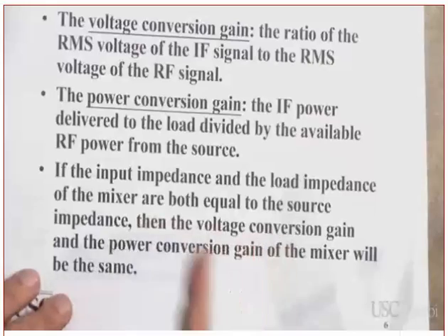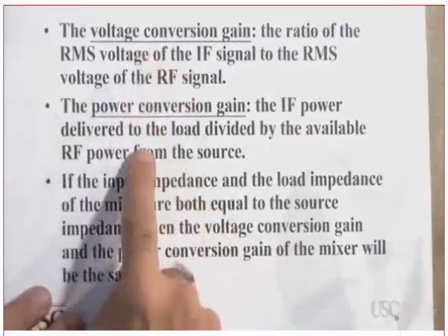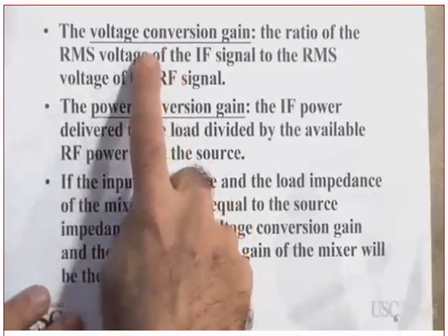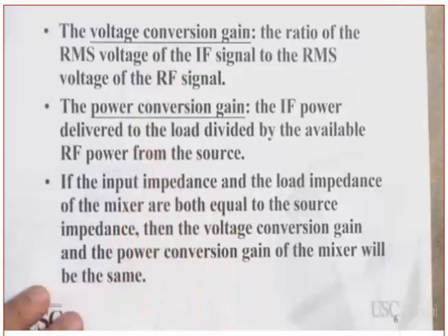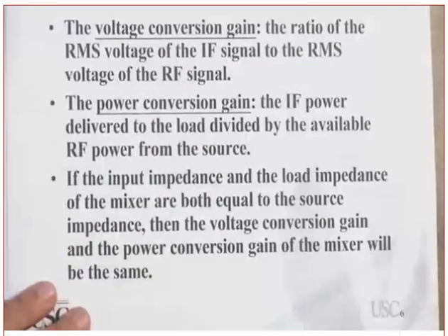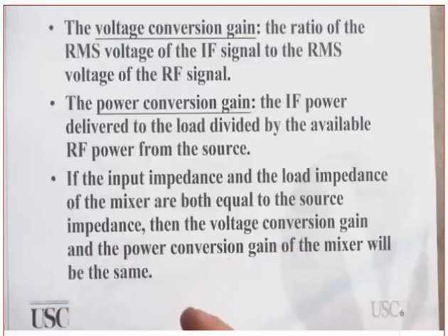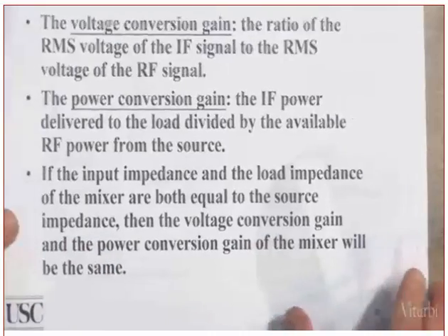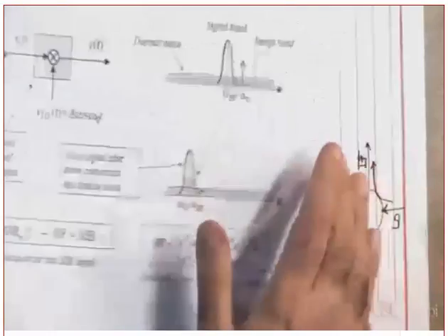But if the impedances are not the same, the voltage conversion gain and the power conversion gain are in general not the same. Did you get this or not? Because the input is measured based on the input impedance. Clear so far? Okay. Now let's talk about the mixer.